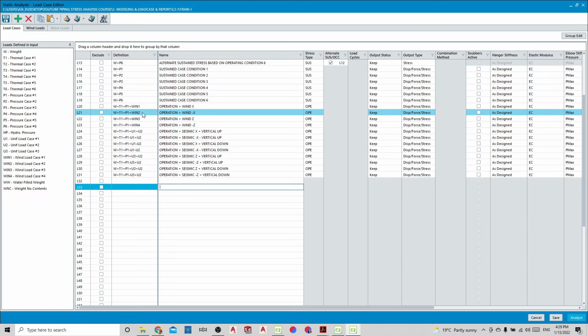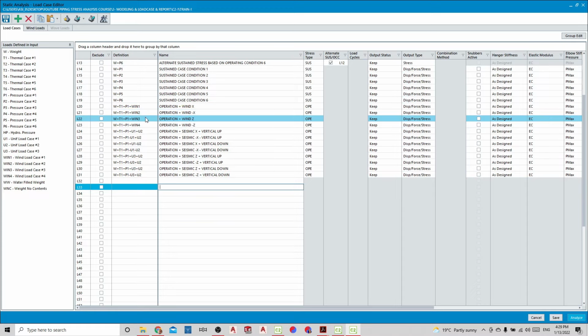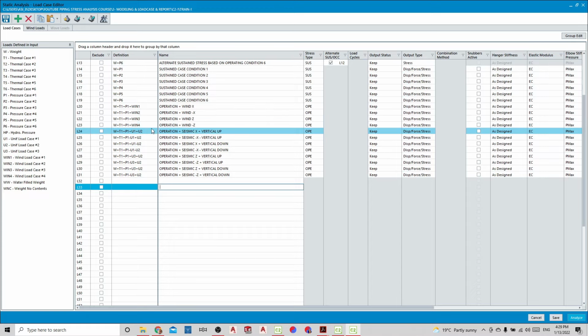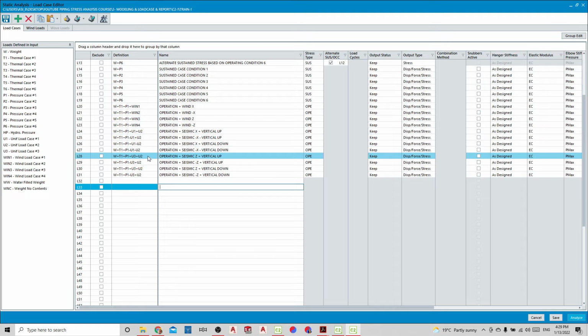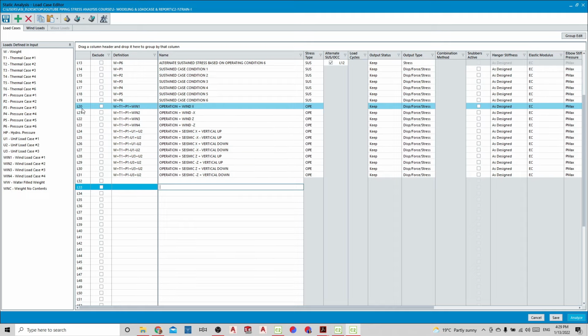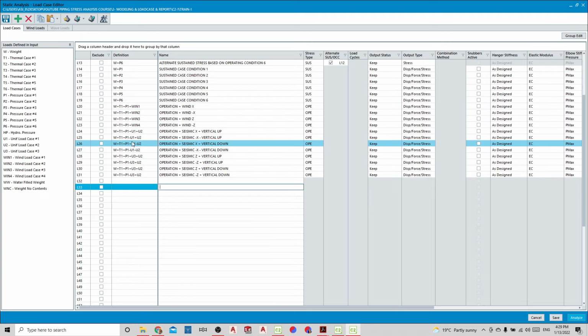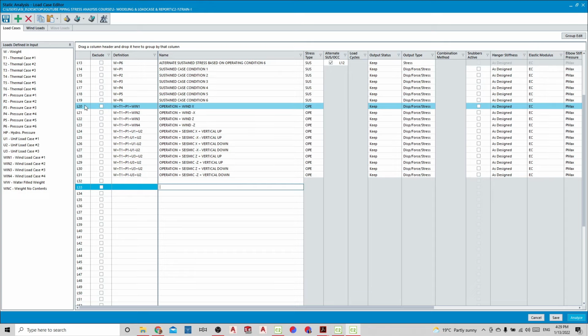Now we need to signify the occasional stresses to apply the hot sustained cases, and how we satisfy and comply with the code requirement. How do we do this? We will do it by subtracting the operational case from this case to have a pure wind or a pure seismic. How will we do this?